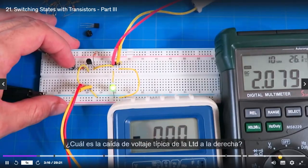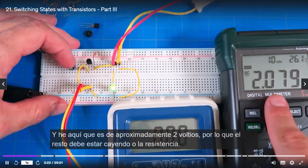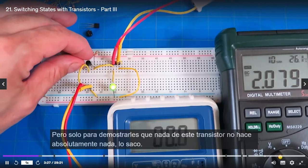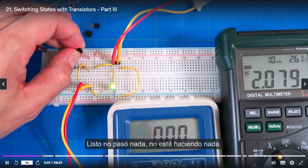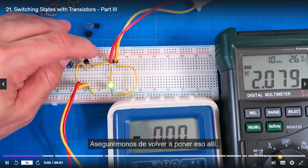What's the LED's typical voltage drop? It's about 2 volts, and lo and behold, it's about 2 volts, so the rest must be dropping over the resistor. But just to prove to you that this transistor is doing absolutely nothing, I'm going to pull it out. Ready? Nothing happened. It's not doing anything, because it's off. Let's make sure we put that back in there.